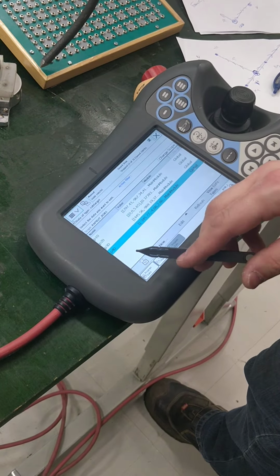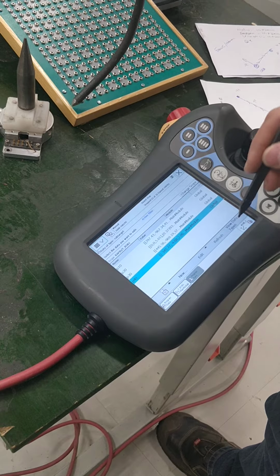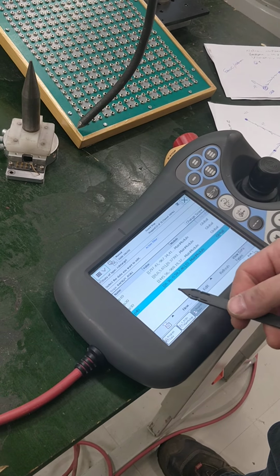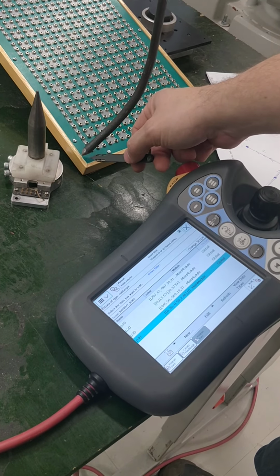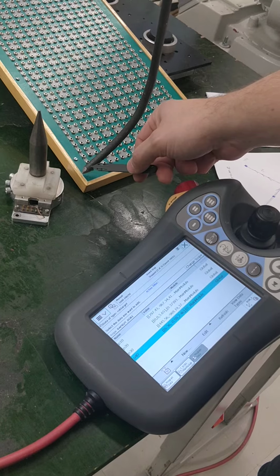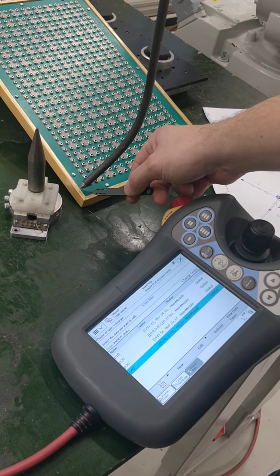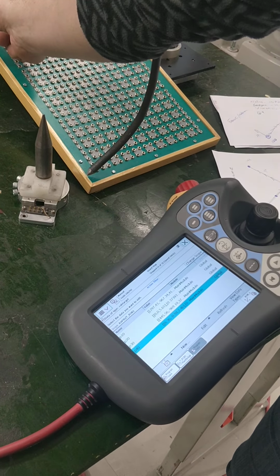Okay, I'll use that B40 a little bit later. But now, if I teach that position, I go to edit and pick modify position, and modify. Now I see that I'm quite near my zero point. But this zero is not the point we meant to be our origin, our coordinate system origin. Our coordinate system origin should be there.